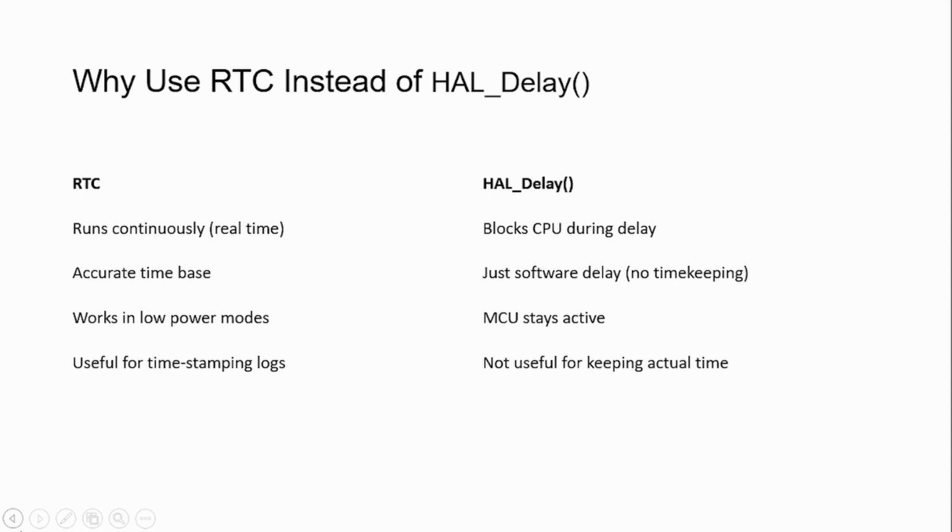Third is it can work in low power mode. As I told you earlier, with a small backup power, RTC can work. Let us say you have some task that you have to perform with an interval of 1 day. In that case, your MCU or microcontroller should not stay active throughout that 1 day. You can use sleep mode, right? And with small backup power, your RTC can work.